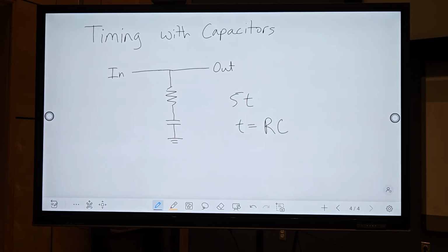No, it's the opposite of resistors. In series, capacitors are 1 over C1 plus 1 over C2, and in parallel, you just add them together. It's reversed from resistors. Think of them as like electronic springs. If you put two springs together in series, the springiness is not added together directly. It is if you have the two springs in parallel. If you remember that from Physics 1. But yeah, those are the right equations. They're just reversed from the resistor equations.